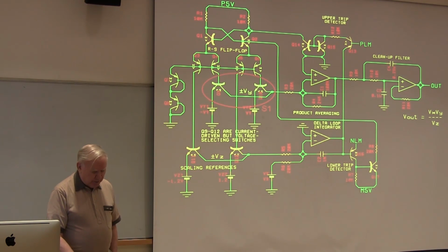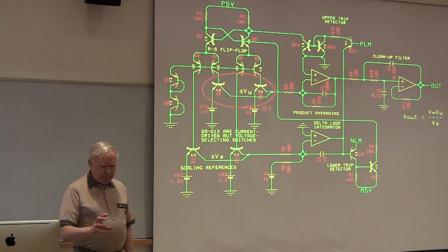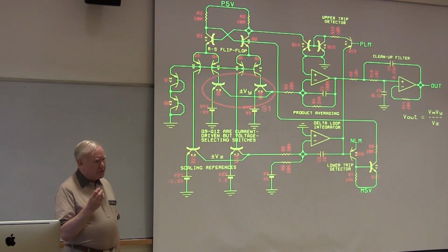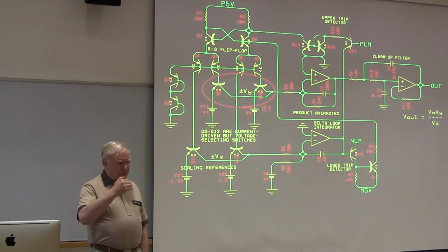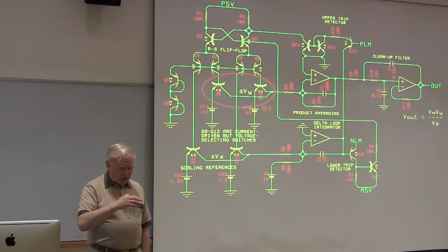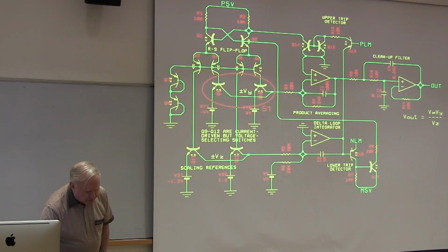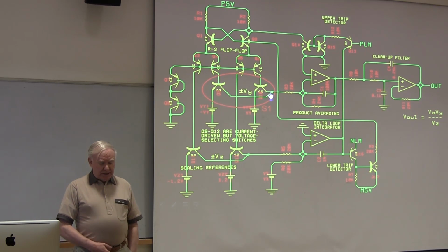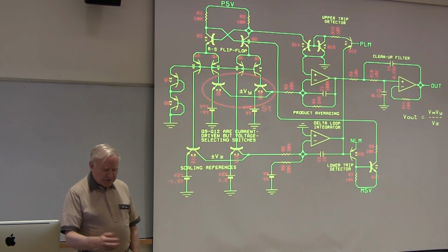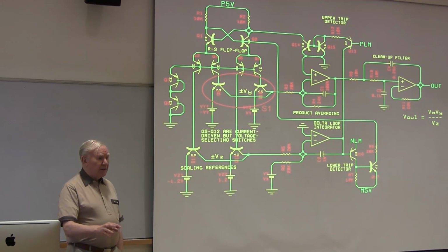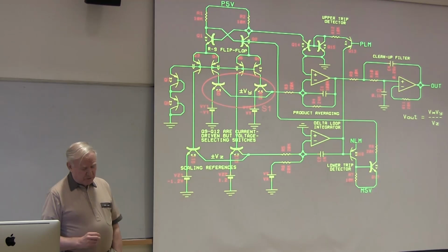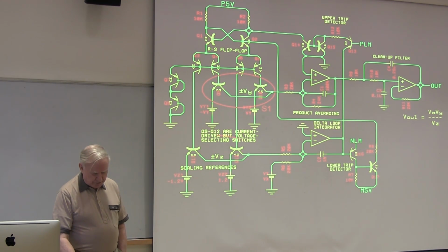And here are the switches. By the way, this is interesting because this is SOI, and in a silicon-on-insulator process, you can use bipolar transistors as switches, provided there's somewhere for the base current which turns them on to go. And in this case, the base current can go into these voltage sources here and here, and we can commutate from the positive or the negative reference to the positive reference using bipolar. And this really works. And it's interesting because the offset of these devices can be very small, just millivolts, which is not what you'd expect from the structure of the device.